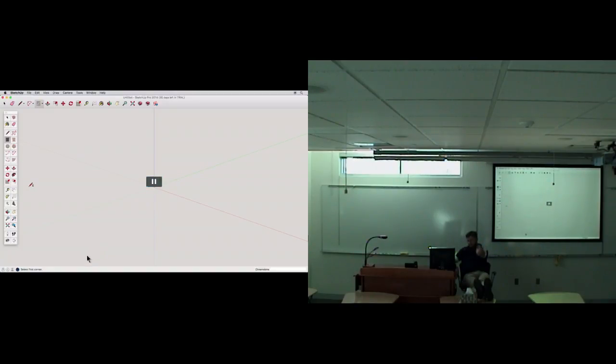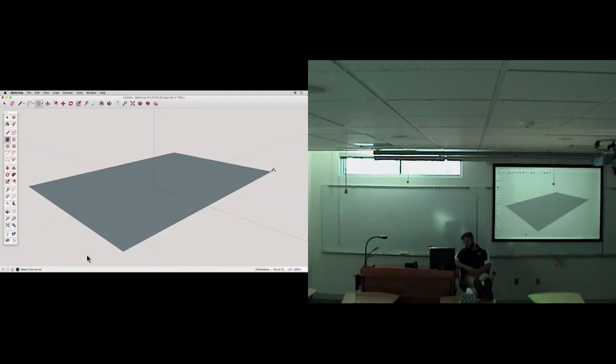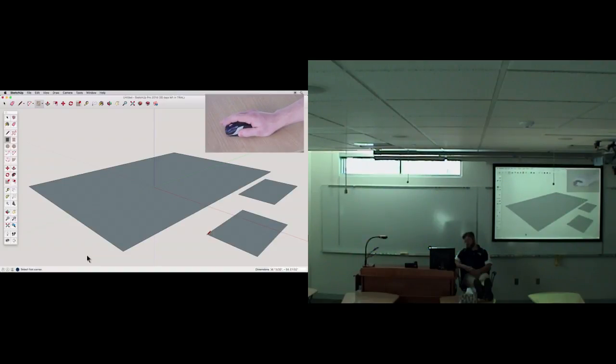Tool, then click once to start a rectangle. Pull away, and click again to finish. A quick note about drawing in SketchUp. Get in the habit of clicking and releasing your mouse button to start and finish most actions. This will be true for almost all of the drawing tools. Unless we specifically ask you to click and drag your mouse button, always click and release to start and finish each tool and action.